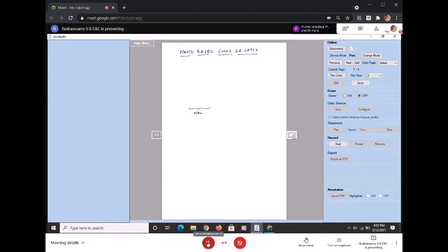I have NAND 1 here and I have NAND 2, so construct each NAND gate using CMOS. How do we connect the NMOSs for the NAND logic? In series. NAND is nothing but the complement of AND, and AND goes with series. So this is one of the transistors.